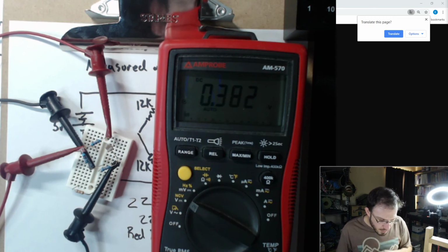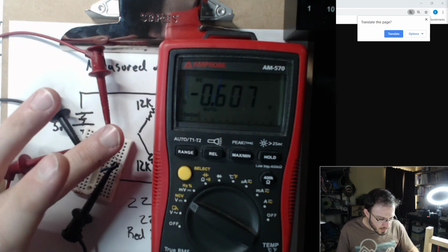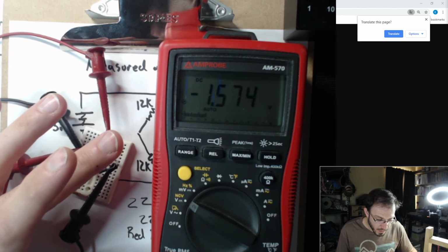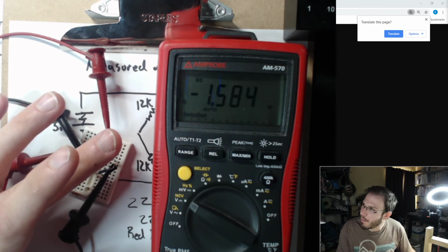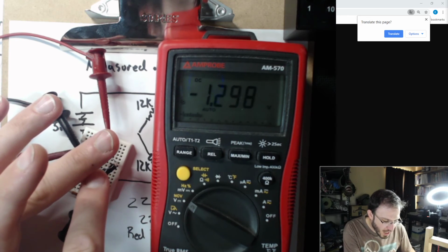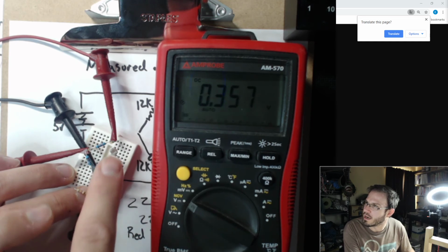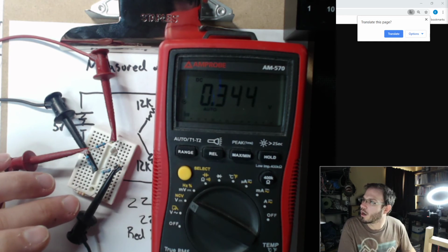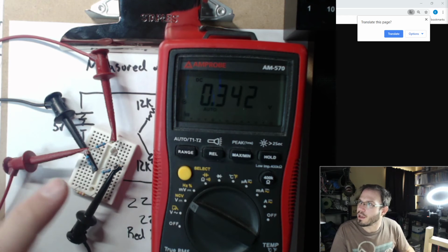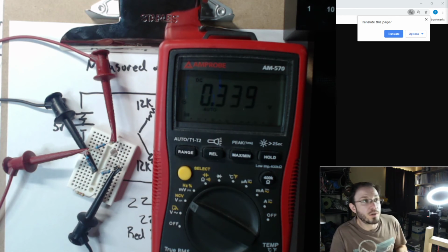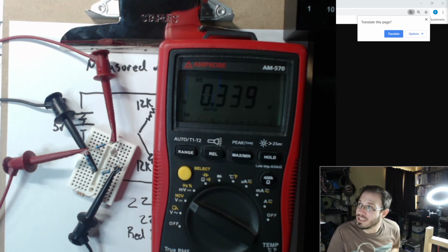so again, 0.38 volts, and if I cover it up, you can see how quickly that changed to minus 1.58. Again, my multimeter is just reversed, and I could probably do a better job of setting up this fixed value resistor over here so that it starts at 0 and goes up to some value. You can adjust the range of this. In fact, if I wanted to, I could also use a potentiometer.